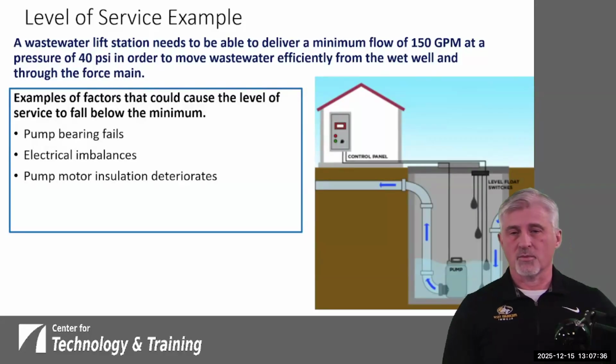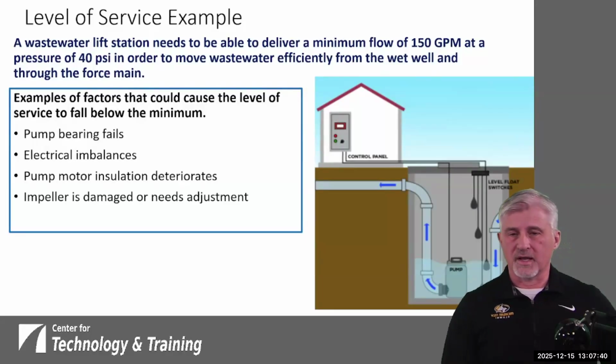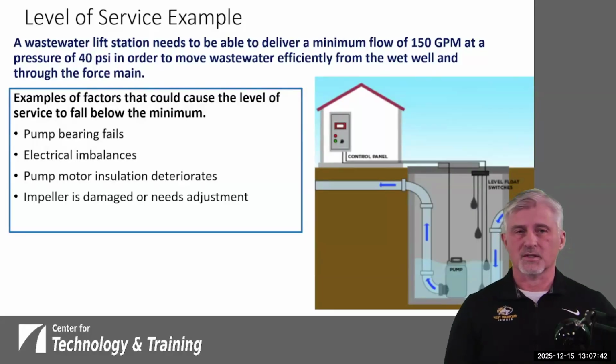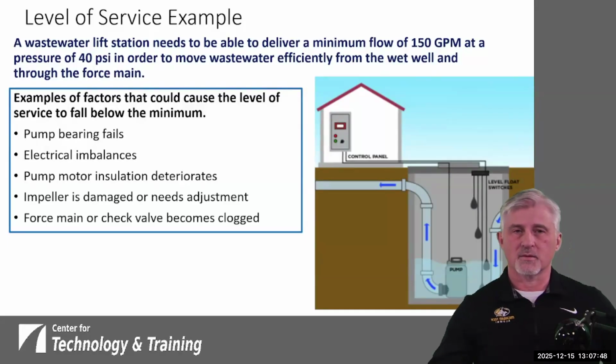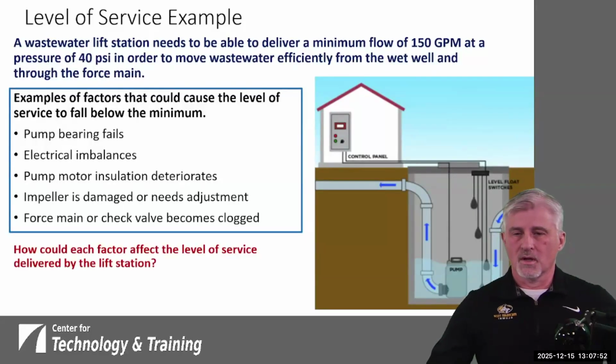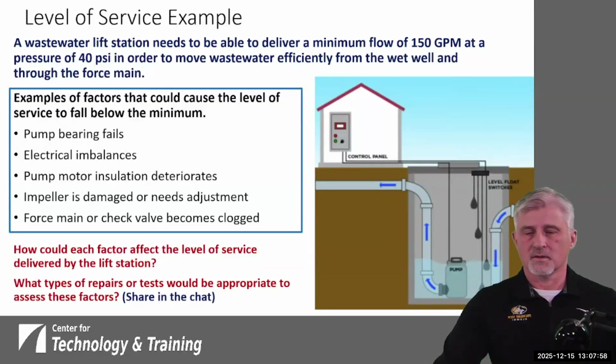The insulation on the pump motor could deteriorate. The impeller could be damaged or it needs to be adjusted. Or the force main or the check valve becomes clogged. How could each factor affect the level of service delivered by the lift station? What types of repairs or tests would be appropriate to assess these factors?